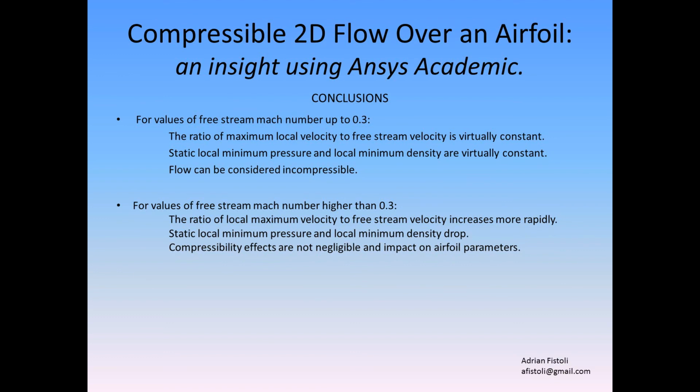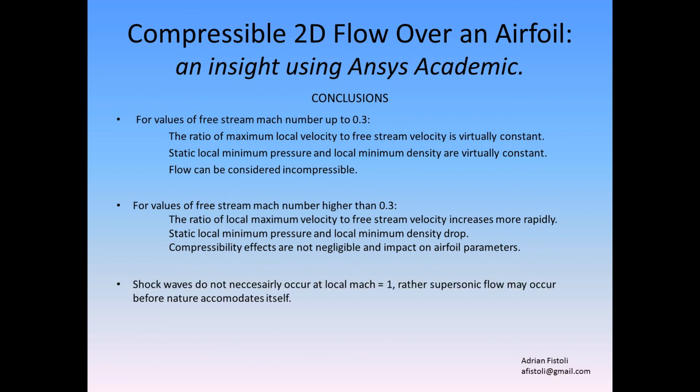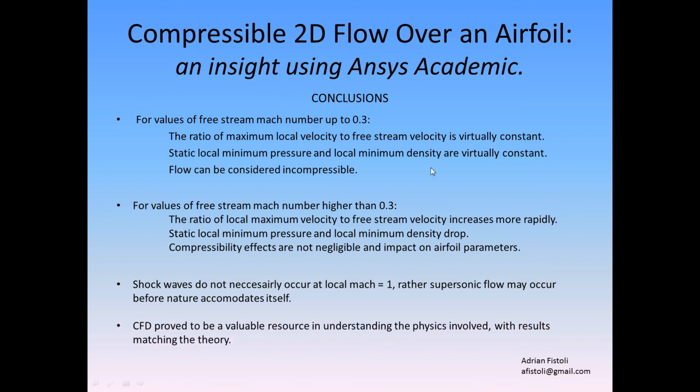On the other hand, shock waves don't necessarily occur at local Mach number 1. Rather, supersonic flow may occur before nature accommodates itself. And last, the CFD proved to be a valuable resource in understanding the physics involved, with results matching the theory.